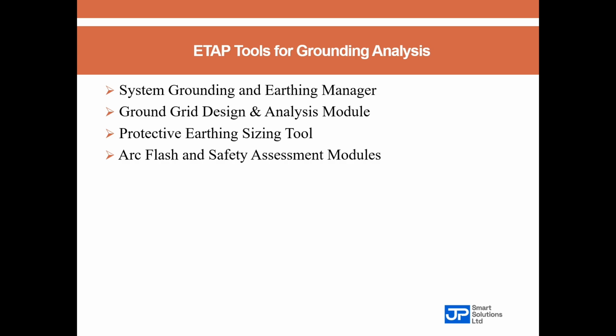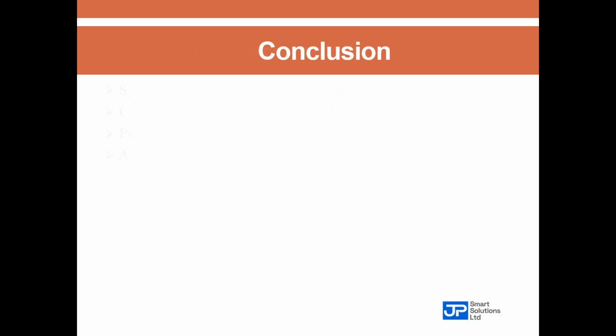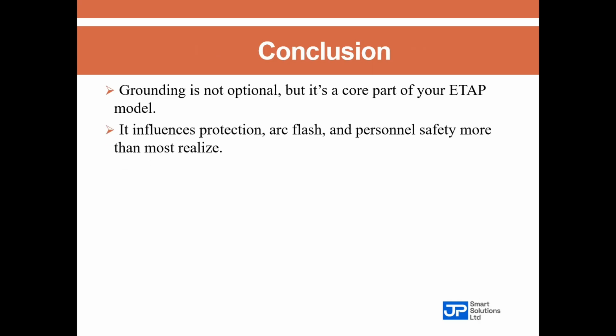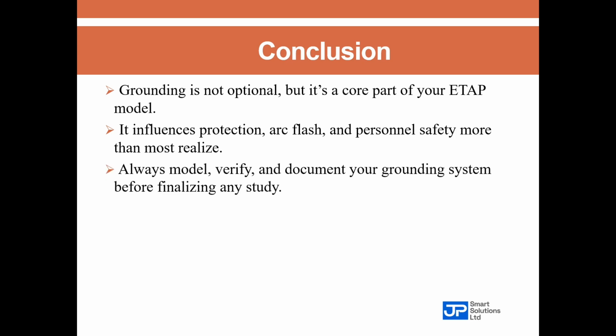Very important question. So let's wrap up. Now we have 3 key messages for you. The first, grounding is not optional. It is a core part of your ETAP model. Secondly, it influences protection, arc flash, and personnel safety much more than most realize. Thirdly, always model, verify, and document your grounding system before finalizing any study.